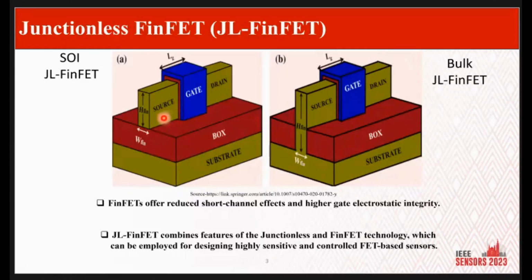These devices are transistors, electrical devices. You measure charge or current. So you measure current, and this current is modulated by charge that can be trapped on the surface. There is another type of device called the junctionless nanowire transistor. You've probably heard most of you of CMOS, complementary metal oxide semiconductor. To make an inverter or to make memory or anything else, you need NMOS and PMOS type transistors, and you create flash memories or inverters, and that is what creates your switch here, 0 or 1.